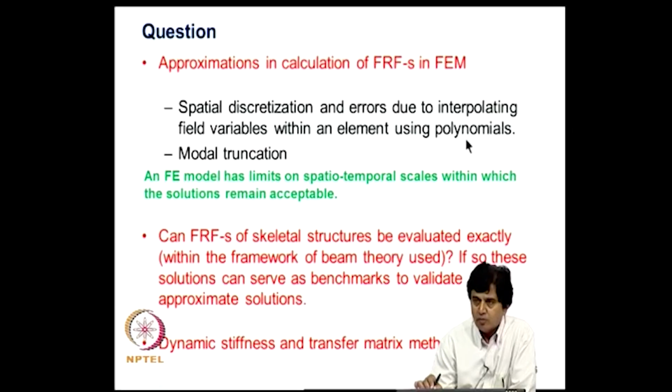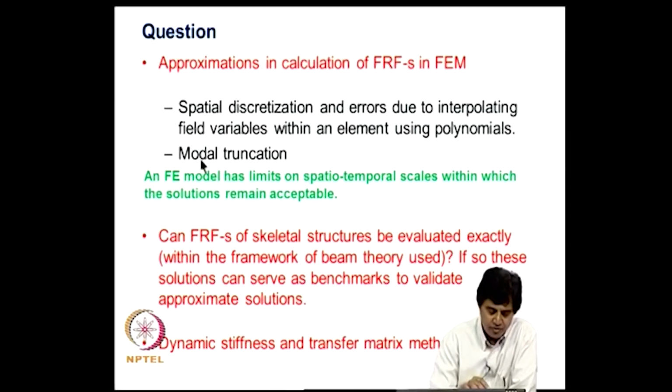Okay. The given domain is represented approximately through a mesh that we adopt for making the finite element model, and within an element we are using the nodal coordinates and interpolating the field variables using interpolation functions. So, both contribute to errors, and if you are using a modal superposition method to derive the frequency response function, there are questions about errors resulting from modal truncation.